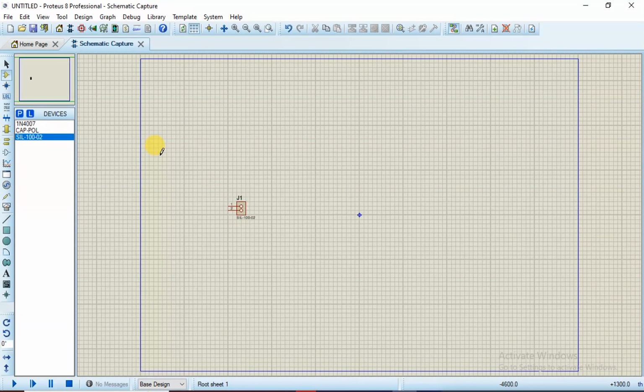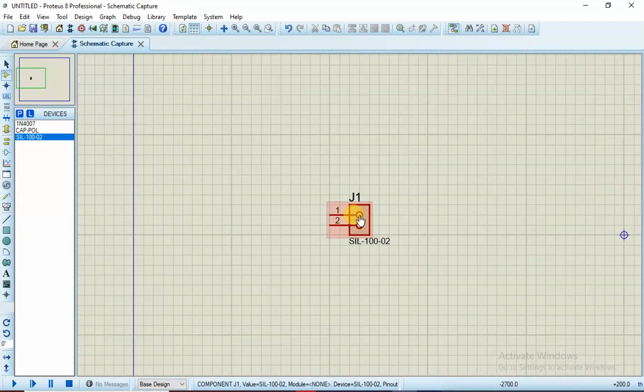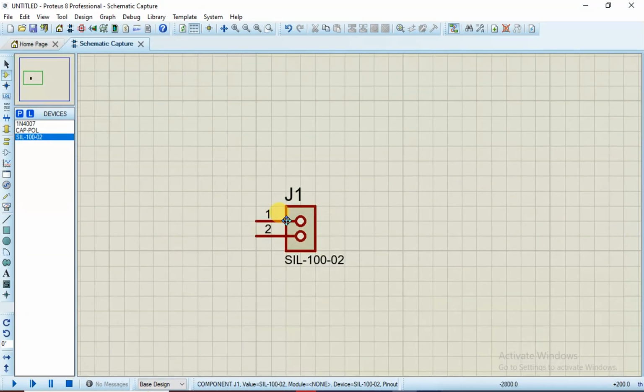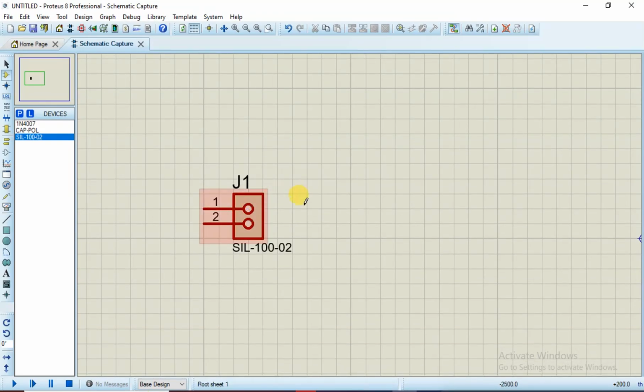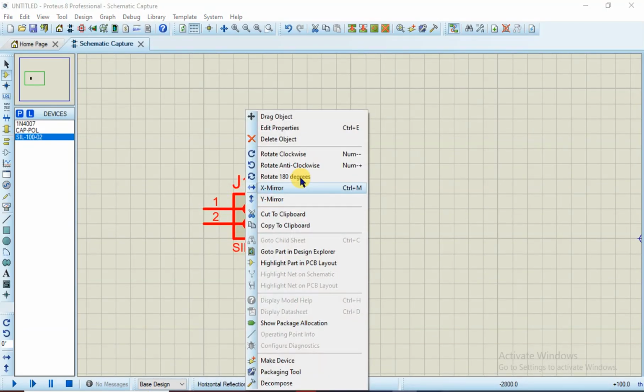To place the components, make sure that you are under component mode. You select your cursor under component mode, then you select the component you want to place. Then when you move into the schematic draw window, it has to show something like a pen. That means it's going to put your symbol. So I'm just gonna zoom in a bit. Very good.